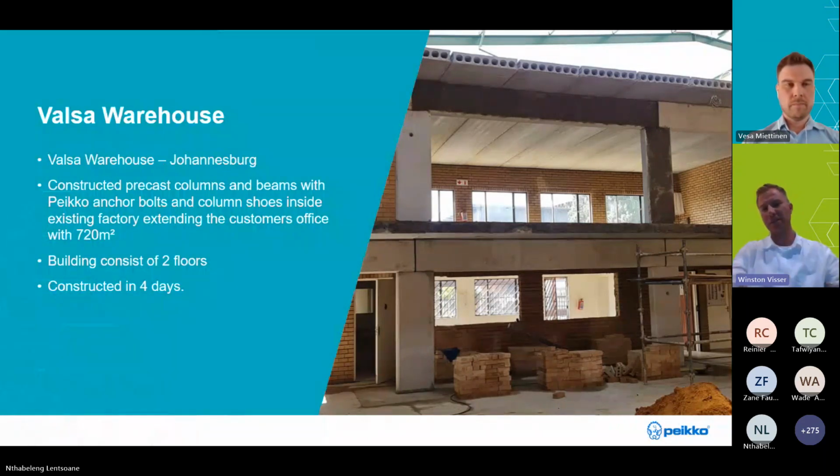So we constructed the precast facade on the inside. We placed the second floor hollow core slab and then lifted the roof. So currently the client has a 3-floor office block. This construction in a confined space, with headroom height problems with the crane, we constructed in 4 days.